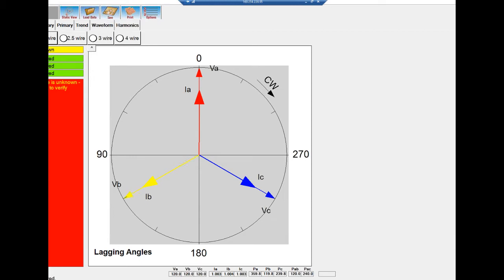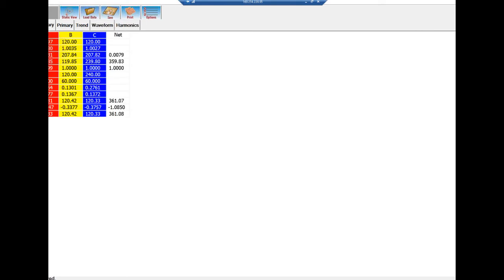Moving on from wiring check, you have the secondary tab. This is raw metrics in a tabular format of what the RW is saying. Volts, amps, line-to-line voltage, total harmonic distortion at the site, raw values for watts, VARs, and VA, all listed out here in a tabular format for you. So you can see listed out for every phase what it's saying.